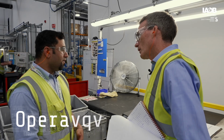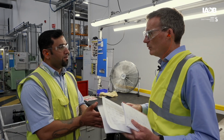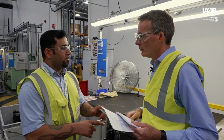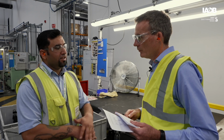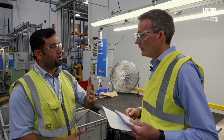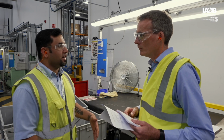Dinesh, we saw earlier that there'd been a customer complaint. Can you just explain a little bit about what happens in this area, the containment area? Yeah, no problem. Whenever we have a customer complaint, the first thing we do is report to everybody in the company. Then whatever stock is made on that particular day, we identify from the traceability. On the SMT labels we have the time and date the part was made. Everything which is in stores, we bring back to this area because it's been booked out. So we book it back in and it goes to our containment inspectors.